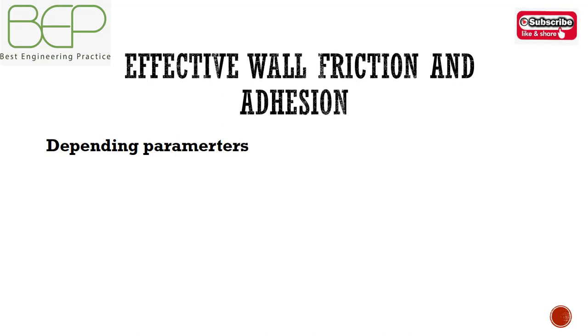Wall friction is created in the soil because of contact with the wall surface, while wall adhesion is the component of shear strength between the back of the wall and the soil it supports. The amount of mobilized wall friction and wall adhesion are a function of the strength parameters of the soils, since the shear strength between the soil and the wall cannot exceed the shear strength along a parallel plane in the soil a short distance away.